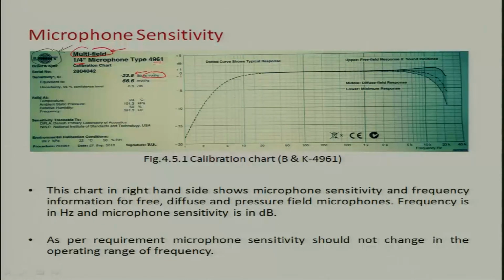Using the relation I explained earlier, LS equals 20 log Y by Y ref, and this is minus 23.5 decibels, then Y equals Y ref, which is 1, times 10 to the power of minus 23.5 divided by 20.